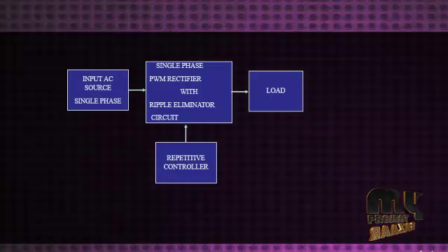A single phase supply connected to an alternating current electric motor does not produce a revolving magnetic field, so single phase motors need additional circuits for starting, and such motors are uncommon above about 10 kW in rating. Single phase AC power systems peak in voltage at 90° and 270°. A cycle completes at 360°.